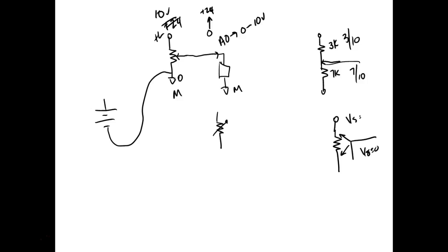And we can have multiple power supplies hooked up to the same common, right? You understand? And then I could take my 10 volts and come up here and apply it to my sensor. All I've got to do is take this and hook it up to one of my M's that's hooked up to my common M that runs through the whole system, right? Does that make sense? Yeah, I could use 5-volt supplies. I could use just about anything I want. All I've got to do is make sure that I do what? That I establish the common for the system. So that's a good question. Any more?